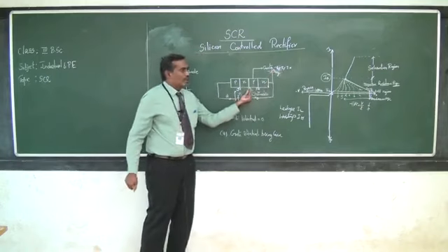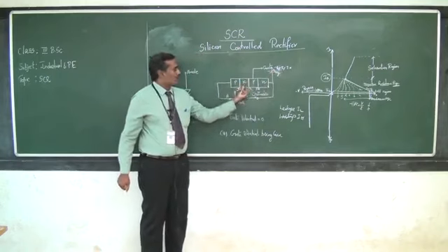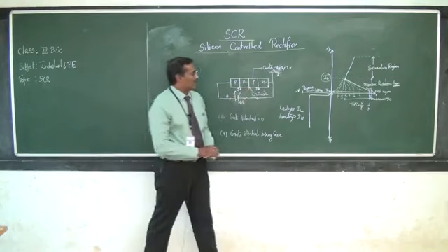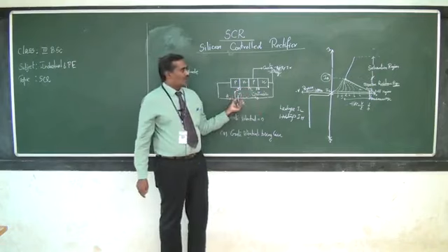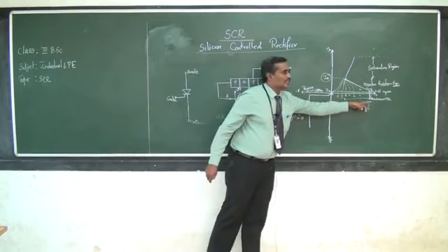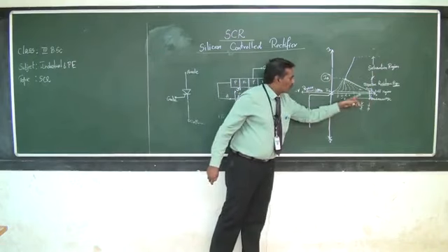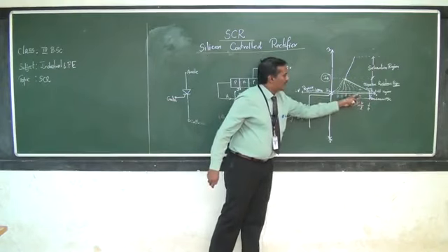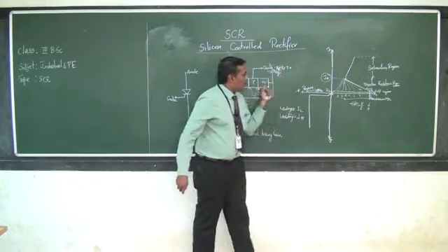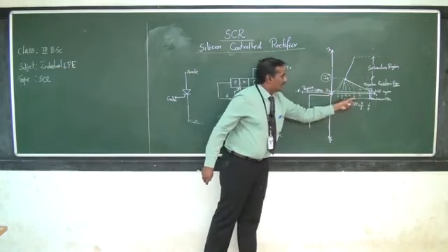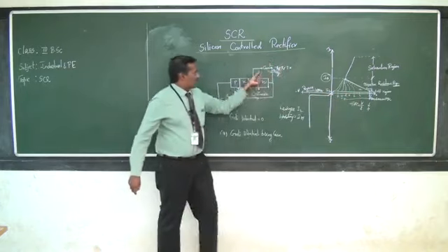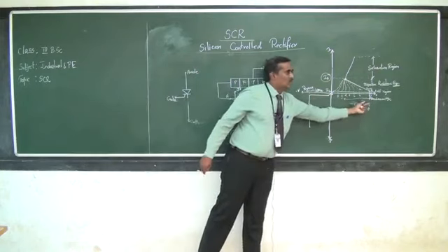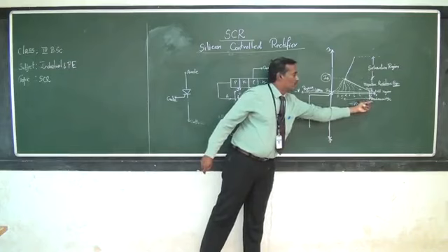Automatically this J2 slowly gets increasing forward biasing. Once it slowly gets forward biased, this SCR will never allow the voltage to reach the breakover voltage. Before that point itself, it starts conducting. So once Ig is applied, before that point itself it starts conducting. The gate potential defines the breakover voltage, and it never reaches the maximum breakover voltage.